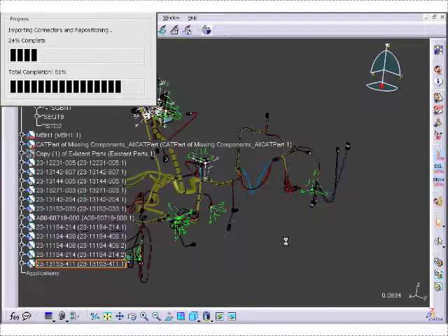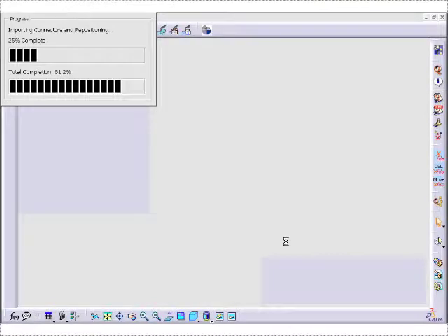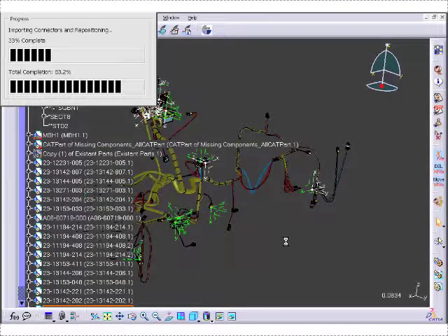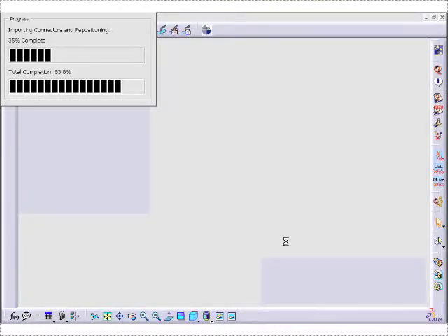So you can see several in this example here. Those are parts that don't exist, but they're at least placing the proper axis system in its proper orientation and position, so that when you do find the part that you want to use, you can easily snap it in axis to axis, and you've got your position.